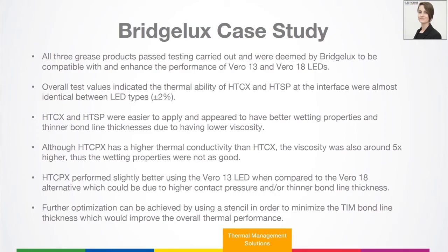So when you're considering the product, it is very important not to just choose the highest thermal conductivity available. How the product wets on your surface is important. If you can apply a thin, even layer, it will have a massive effect over whether you have gaps or air pockets.